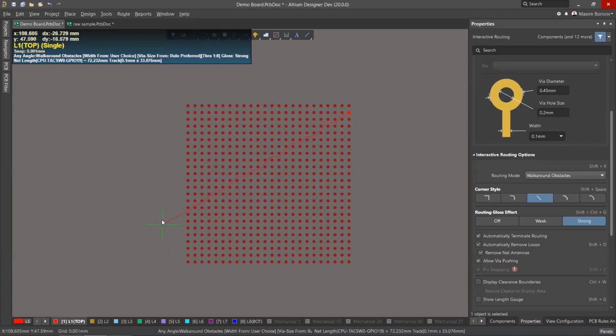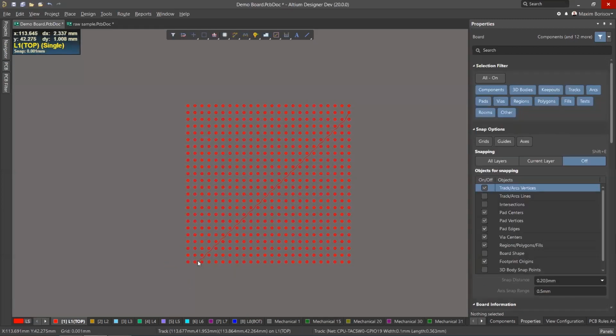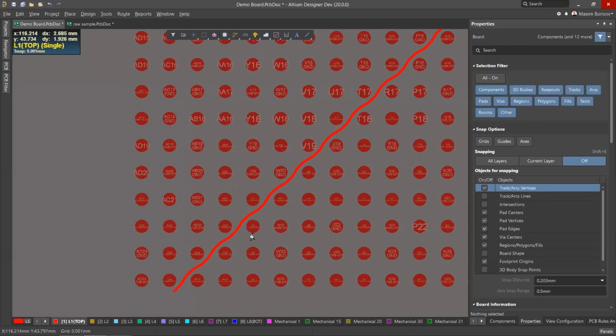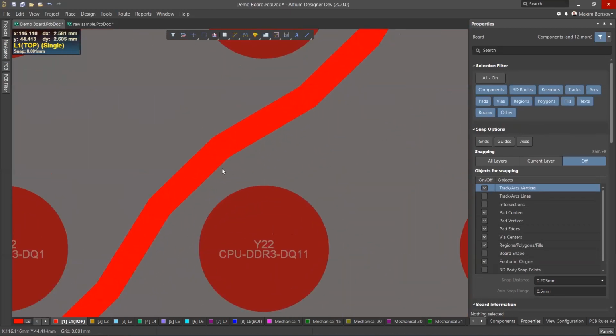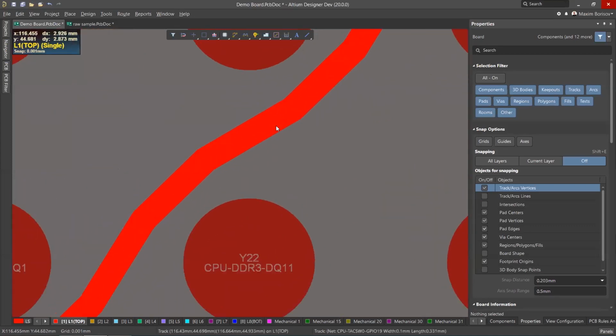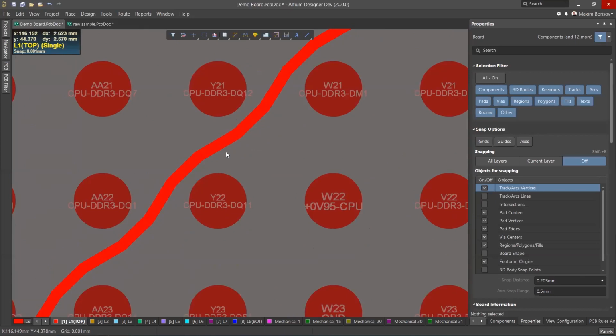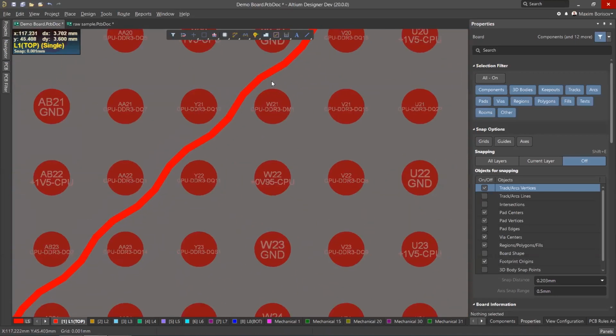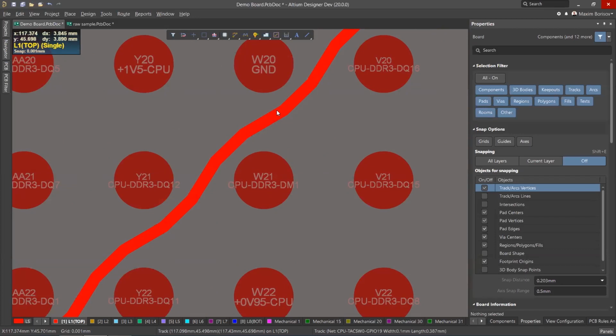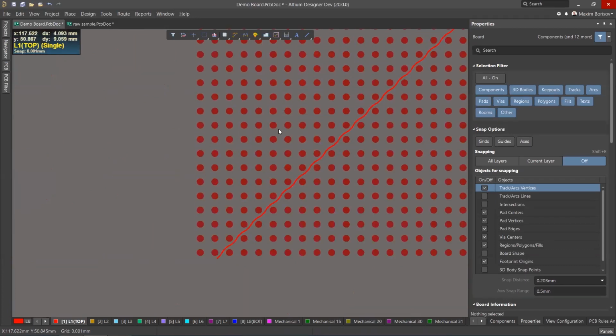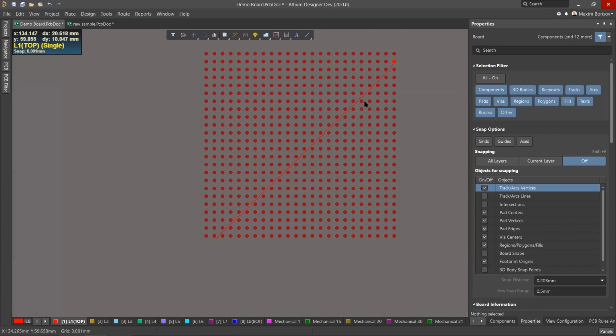Maybe this, this, this. So you can see it takes sub-seconds to perform. The whole connection is made with tangent arcs. For now it's not arcs, it's odd angle segments, but they are tangent as well. So you can see it's made perfectly and placed efficiently through the whole channel. And basically, it takes sub-seconds even for larger BGAs like 1K pins, 2K pins. It's a very fast-acting feature.